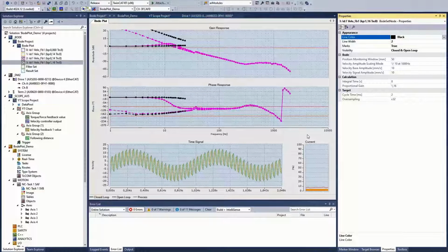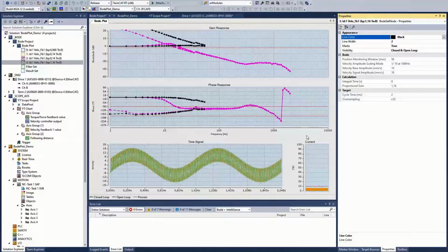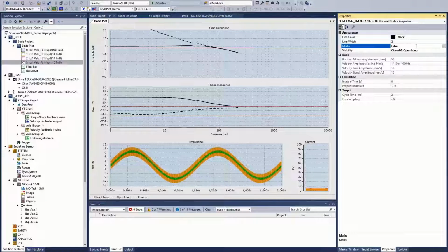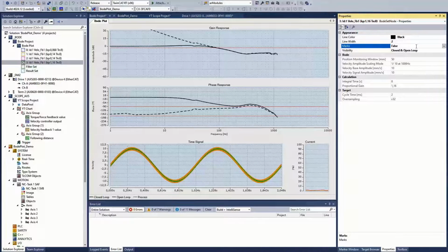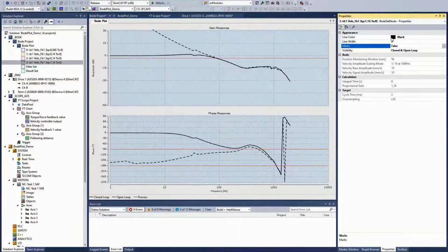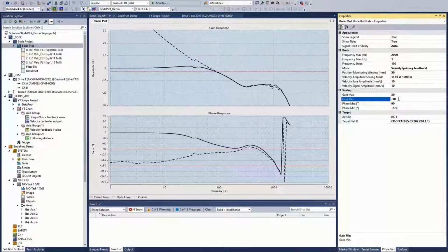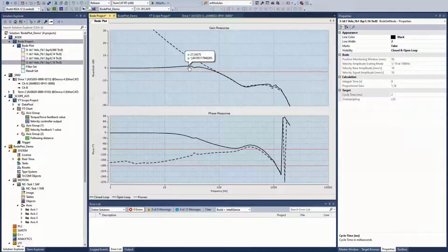So you can see the closed loop is for higher frequency at 0 dB, which means the system is reacting perfectly. And at the same time, there is hopefully no spiking anymore, no peaking. That's the case. We can check maybe in detail some figures, the bandwidth and the peaking. The peaking here is a bit more than 1 dB. This is acceptable. And the bandwidth is around 80-85 Hertz. So a massive improvement in comparison with the default situation and no issue at higher frequencies.